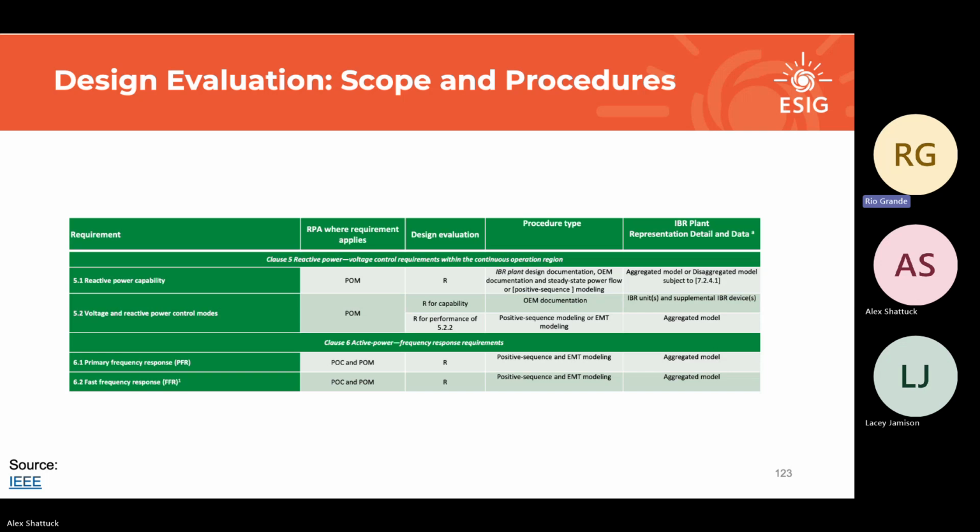On the low side, you're probably going to get lower than 0.95 voltage at your farthest turbine, which means summing up all of the reactive power capabilities, even including losses, you're not going to get the right answer, right? So it's very important for disaggregated. I think the note in there, the extra section was disaggregated, but here's a bunch of language I had to write to basically say do it at your own risk, because there's a lot of perceived extra work for disaggregated model building. So is there really?